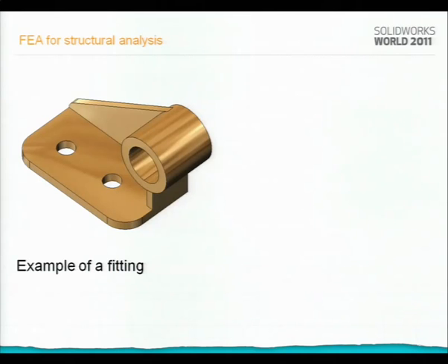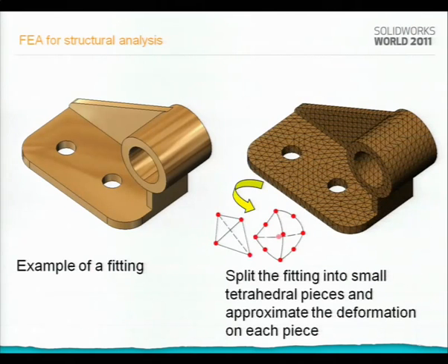This is a solid model where the 3 dimensions are important. So in SolidWorks Simulation, we have 2 types of solid elements. In this session, we are going to use all the elements that SolidWorks Simulation presents. So it's important to understand what these elements are. We have the 4-node tetrahedral element and the 10-node tetrahedral element. In other words, we have a draft element and a high-quality element.